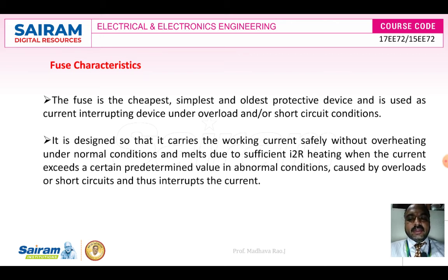It is designed so that it carries a working current safely without overheating under normal conditions. Under normal conditions the fuse should not overheat and it should not melt. It produces sufficient I square R heating when the current exceeds a certain predetermined value, caused by overloads or short circuits, and this interrupts the current.